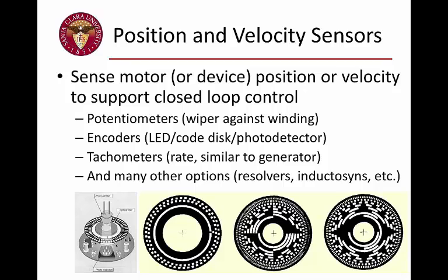There are other things called encoders, and they can be used for position or velocity control or sensing. You can see the graphics at the bottom showcasing a little bit about encoders, and the lower left portion is an encoder device itself, and it shows an optical mask, which is that disc with all the little white dots on it. The dots imply a hole or a transparent portion of the disc so light can shine through.